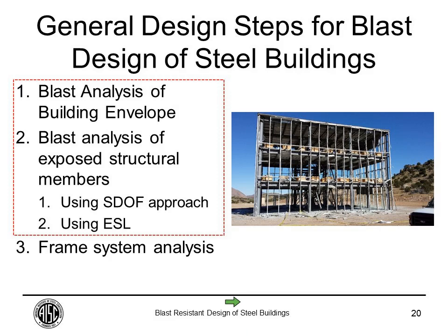After you design your envelope to resist the blast load, that envelope collects the loads. Remember, we talked about that. For a member to be efficiently or effectively loaded by blast, it needs to have members that collect the load and transfer it to it. So the second step, which is probably what we're going to concentrate on in this presentation, is looking at the analysis of the exposed structural members in a steel building.